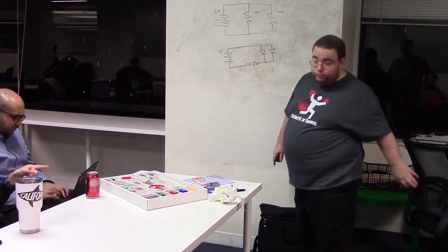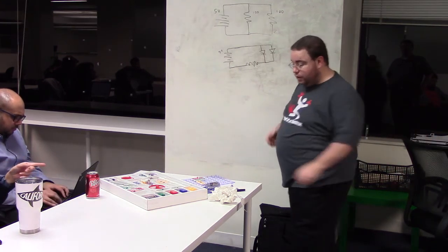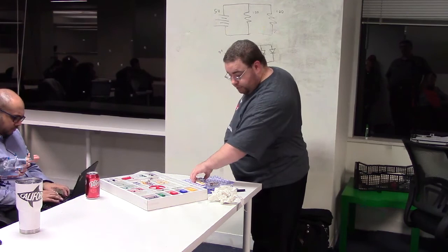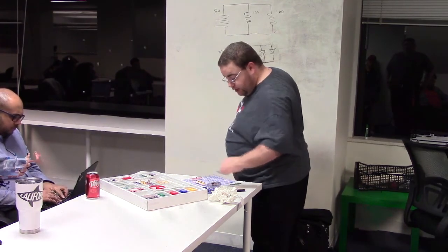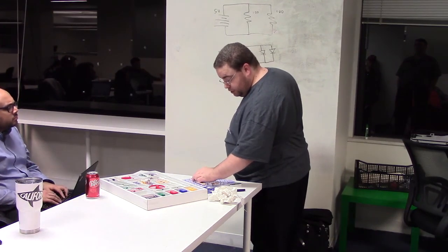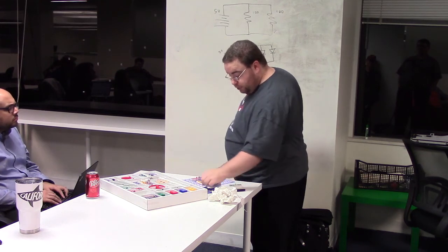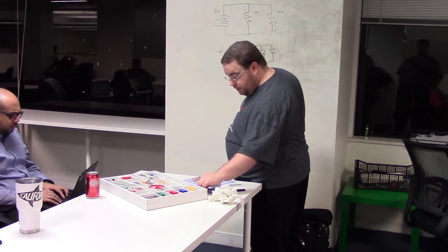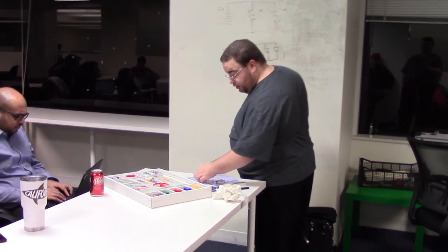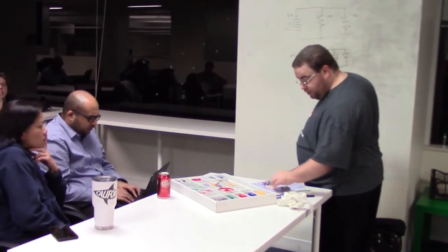So you can exchange one of those for a bulb, and everything should still work, right? Yes, except the bulb probably is not going to light up very much because we have the resistor in series with it. The bulb needs a lot of current to operate. So if you have a resistor in series with the bulb, it's probably not going to work.